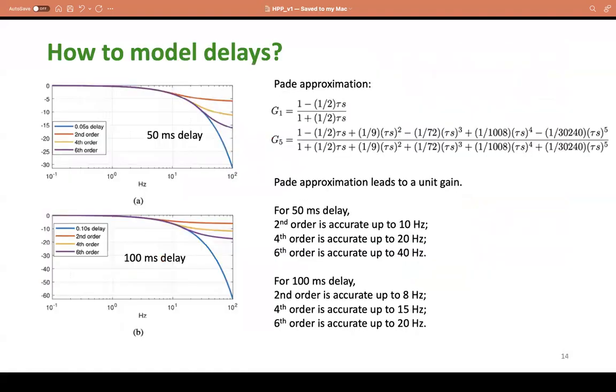Okay, so we have talked about all these delay influences. So now how do we model delay? In this case, the software package is usually written in the state space format, so you have to convert to analytic format. So e^(-Ts) cannot be modeled, cannot be simulated or analyzed. So one solution is this very popular one called the Padé approximation.